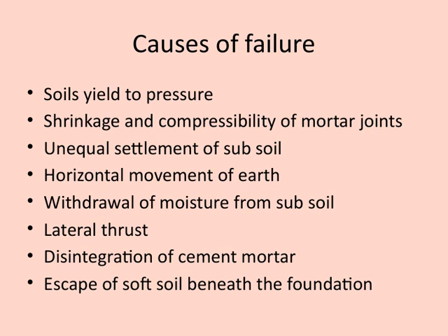Lateral thrust, which is the sideways force exerted by soil or water pressure, can push against the foundation walls and cause failure if not properly designed for. Disintegration of cement mortar, perhaps due to chemical reactions or poor quality, weakens the bond between the foundation and the structure. Lastly, the escape of soft soil beneath the foundation, often caused by erosion or improper compaction, results in a lack of support and potential sinking or tilting of the building. Understanding these causes helps us identify potential issues early and design foundations that are resilient and durable.